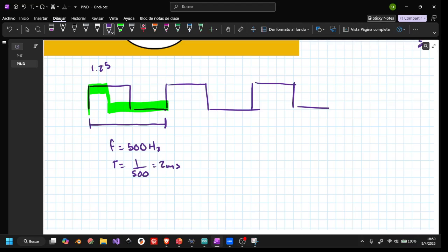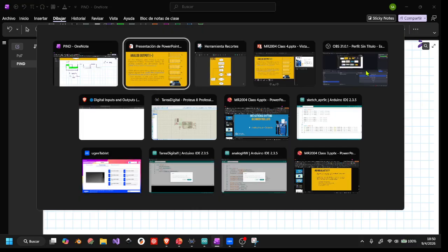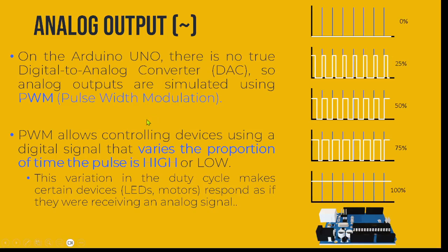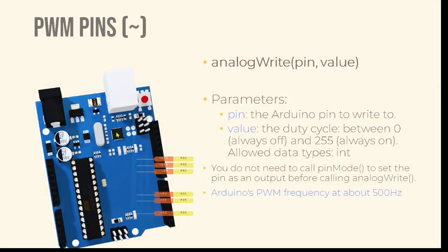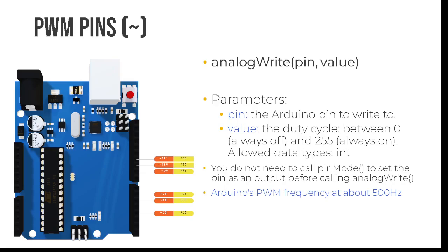Okay, in the Arduino Uno, our PWM converter is 8 bits. So we can convert 256 values, right? So we can divide the 5 volts in 255 equal values, right? I can generate whatever value in that signal, right? To send that in the Arduino, for digital one, we use digital write. For the analog one, we are going to use analog write.